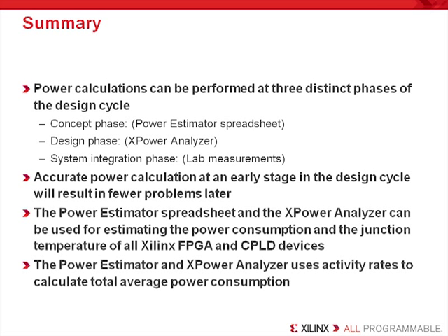Now let's wrap up this module with a brief summary. Power calculations can be performed at three distinct phases of the design cycle. At the concept phase, they can be estimated with the Power Estimator spreadsheet. During the design phase, they can be estimated with the XPower analyzer, and of course this is after the design's been coded, synthesized, and implemented. So it's a better power estimation than the concept phase, which is the use of the Power Estimator spreadsheet.